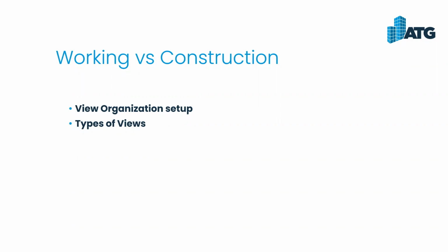The MEP Productivity Pack starter project views in this category show flows and velocities in HVAC, hydronic, and plumbing systems, and they each have color fill legends as well, so that everything is color coded depending upon what type of discipline you're working with. So those are available for you to use.